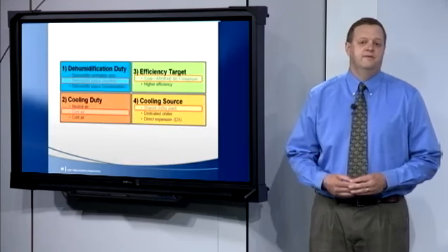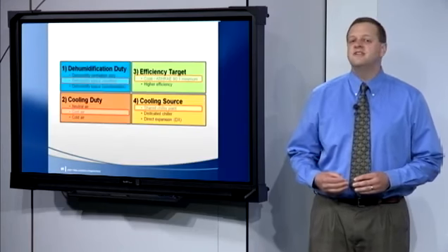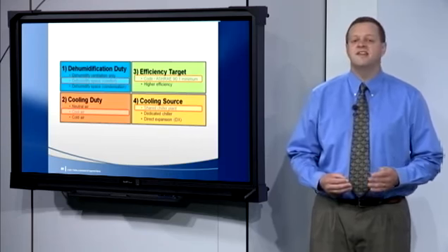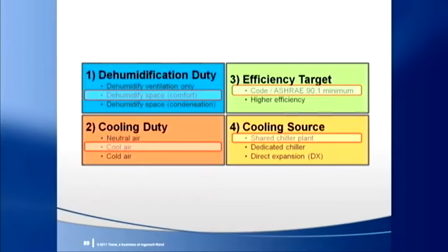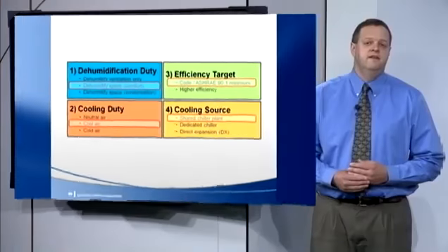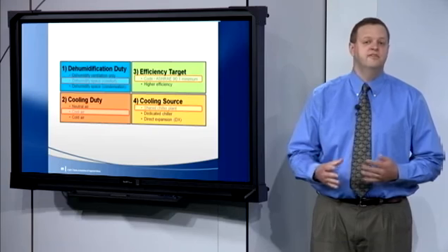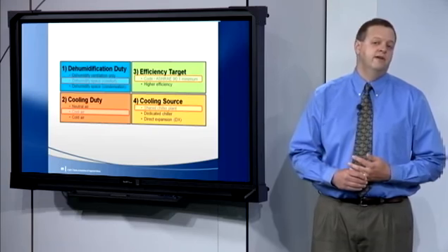Restrictions on the cooling sources available for a given project may also drive the decision to use a series configuration, but it might require using a series desiccant wheel rather than a sensible heat exchanger. As an example, if the system requires 46-degree dew point air from the dedicated outdoor air unit, what can we do if the only source of cooling on the project is a central chiller plant that makes 45-degree water? A cooling coil can't make 46-degree air if it only gets 45-degree water. An alternative is to use a Type 3 desiccant wheel in series with the cooling coil. This can also meet the prescriptive energy recovery requirement of ASHRAE 90.1.